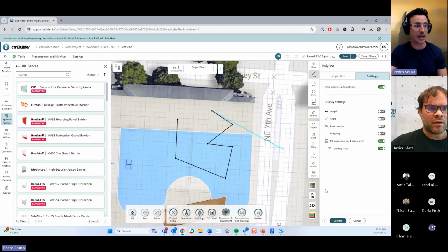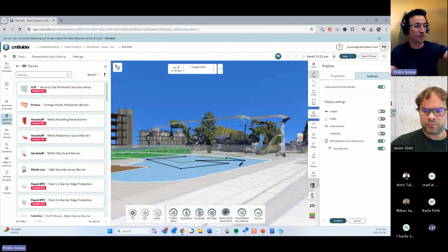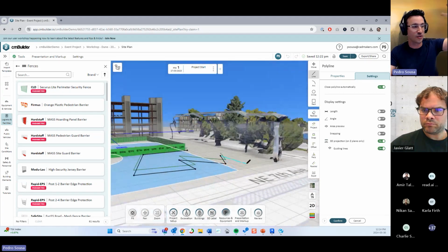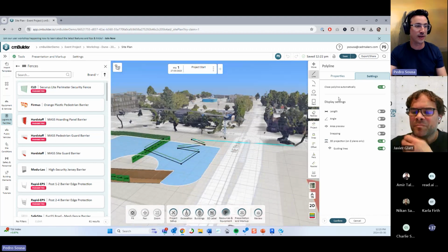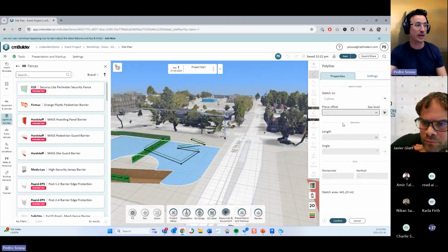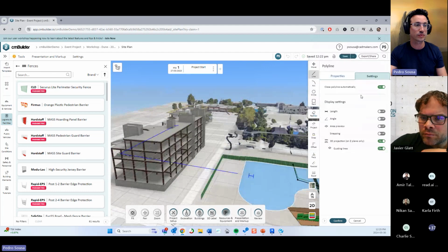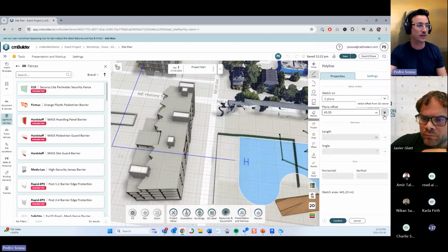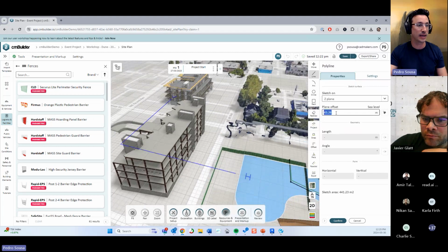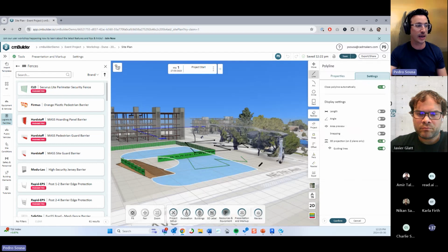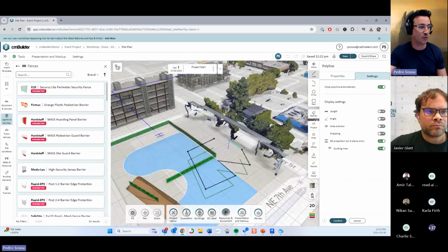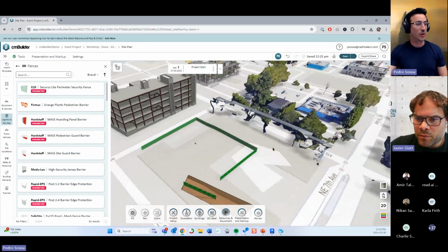The 3D projection and guidelines over here is just to show you what is a 3D projection of that sketch onto the terrain, and also the guiding lines will show you if I move this plane up. So if I move my sketch upwards, you can see that it's projected down onto the terrain, and the guiding lines are to show me where my point is going to fall on the terrain. So that dashed line over there. Cool.